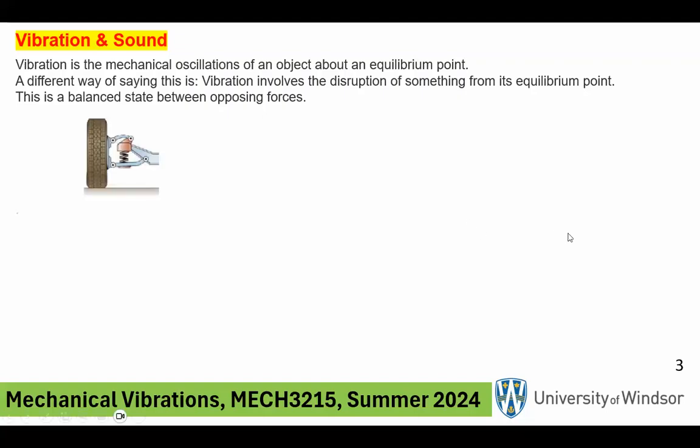Now, let's take this situation that you are mostly familiar with, and we have a suspension system here. Essentially, it is a four-bar linkage. You can see that we did this in the CAE course last summer. So we have link one, link two, which is the tire, link three, and link four, which is essentially the chassis of the car. Now, obviously, if you go over a bump, this starts vibrating up and down or in some other direction. At the end of the day, this is a very complicated setup, but we're going to replace it as a first attempt with a spring and a mass.